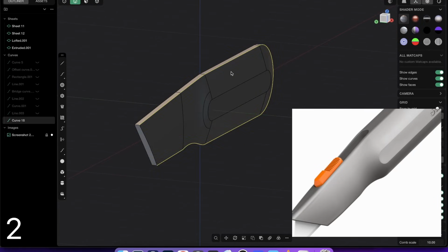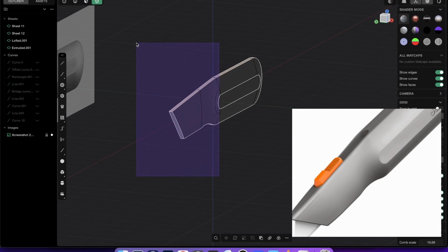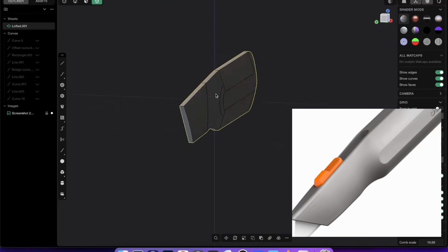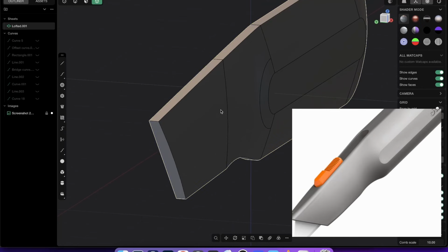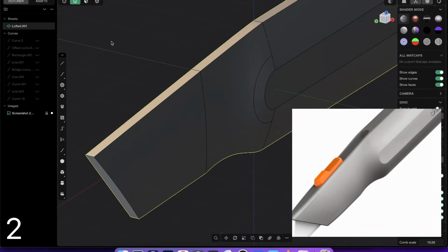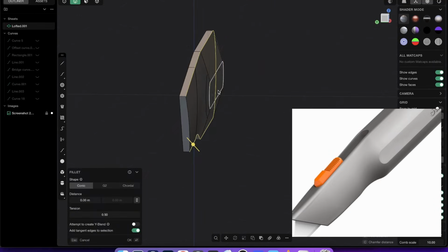Press 2, select this curve, hide it again, select object mode, select all of those surfaces and join them. So you have one sheet, and we have to do one more important thing, because probably you will not be able to give here everywhere a nice fillet. So you can try that if you press 2 and if you alt click, so you just select this whole edge loop.